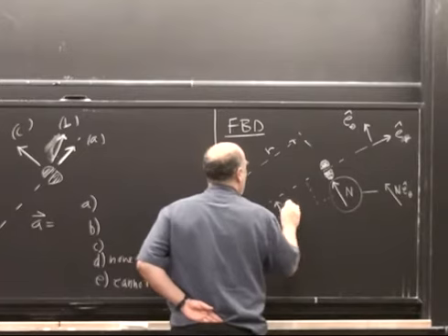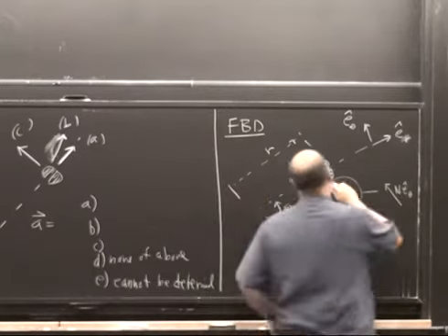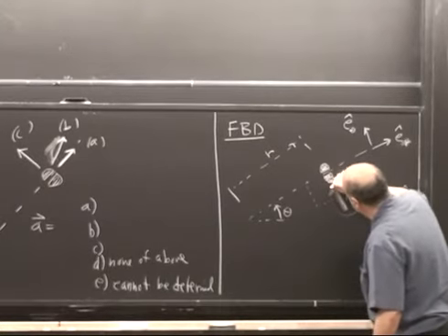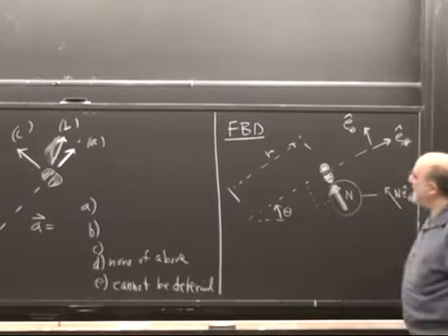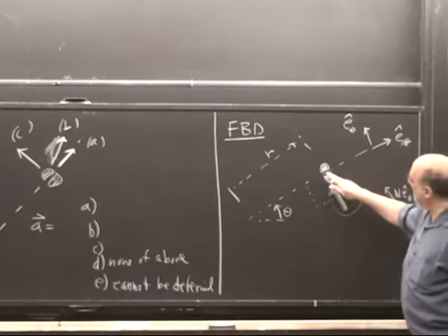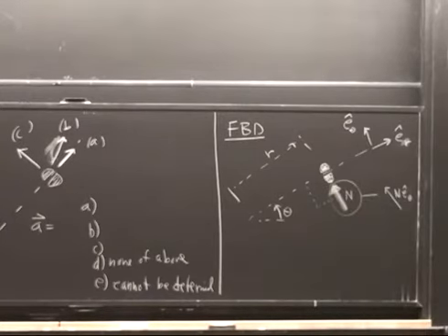I try to draw these r and theta far enough removed from this and drawn differently so that there's no confusion about which is forces on the free body diagram and which are little dimension lines. And I draw the force on the outside, so you see this is acting on this thing. Really, I'd like to draw it in there, but it gets confusing. Any problems or questions about this free body diagram?